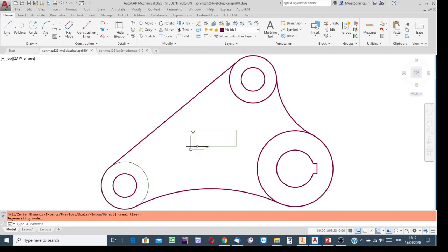If you need to see the projections of hidden features as distinguishable along their lines of action via having enough number of dashes, then you should manually change the length of the dashes, writing this command LTSCALE, you know. Then from the list that drops down while you are writing this keyword, bring the cursor onto the one that is LTSCALE.